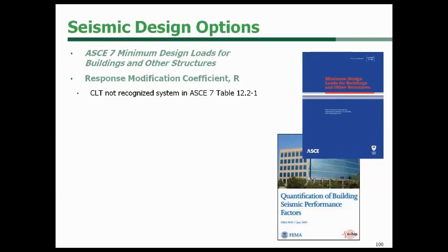There is also an option you could use a prescriptive lateral system in conjunction with a CLT frame. So if you wanted to use a steel frame for your lateral system and use CLT for your gravity loads, that is allowable as well.